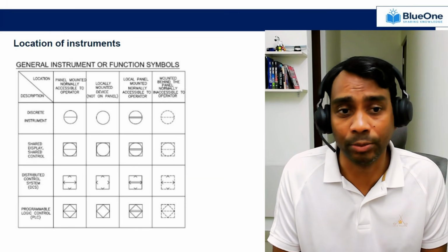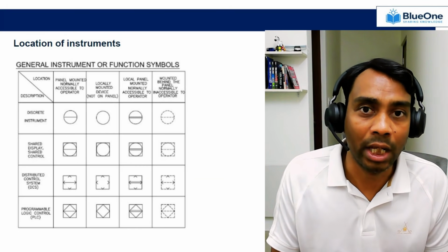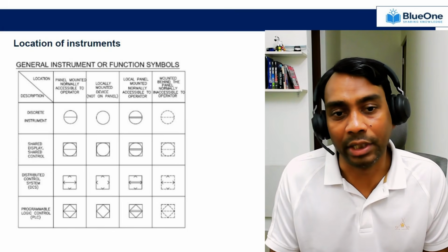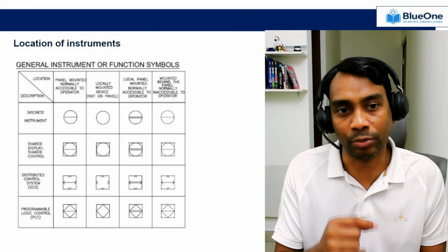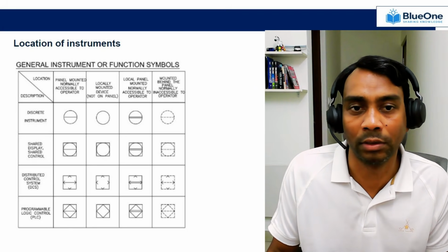and there is a distributed control system as well as your interlock diagram. So any particular symbol with the diagonal or the diamond indicates that those particular instruments are associated with a particular interlock in the plant.